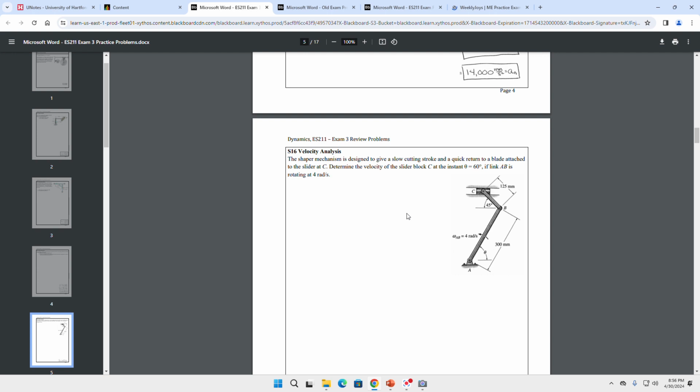It's a tough problem. The fundamental thing to watch out for in the rigid body collision problem is to make sure that you're using the localized velocity of the rigid body as part of the coefficient of restitution. That's the spot. The coefficient of restitution doesn't care about the angular thing. It just cares about what it's seeing right there where the particle is hitting it. So that's the velocity that you have to put into the coefficient of restitution to be able to get it into interaction with the rest of the body.